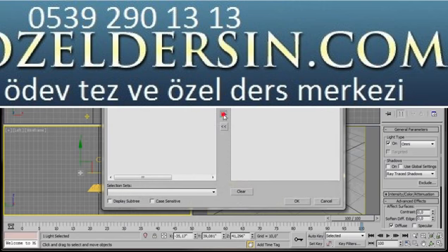So let's go up to the material editor or just press M on the keyboard. We're going to use a mental ray Arch and Design material, so I'll just drag one out. Double click on the material to open it, and then we're going to change the name. We'll just type in ground.